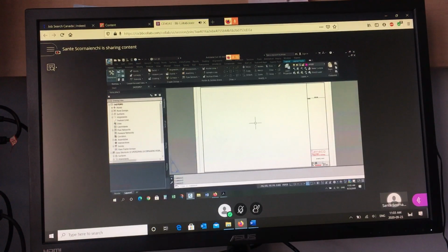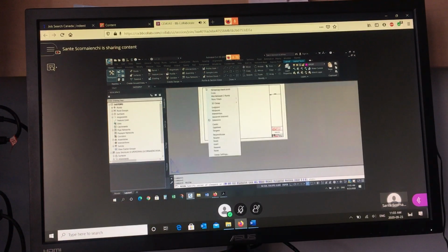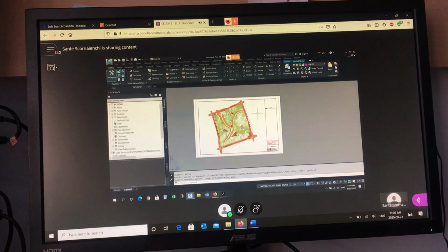Yeah, ready to go. So now I type in mview, and I cut a hole in paper space to look at model space. I'm going to use the whole field, so I'm going to go from endpoint to endpoint here. And when you do that, it's going to show you model space through the viewport, and it'll zoom extents, so the scale is going to be off. Okay, so we need to establish scale and do a little bit of housekeeping. So that should be review for everybody, creating a viewport. Again, I'll move the frame over. Right, let me do this, and I'll get back to it.